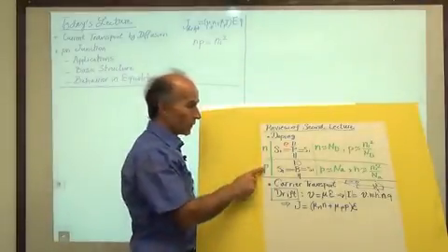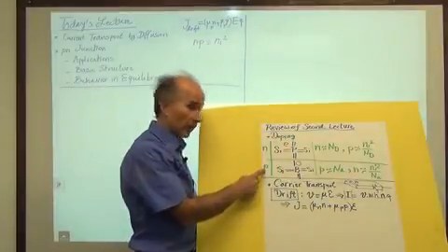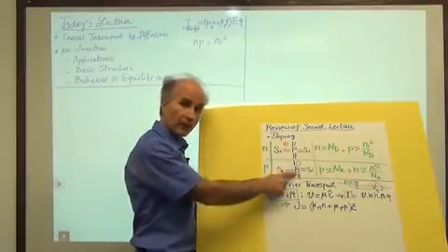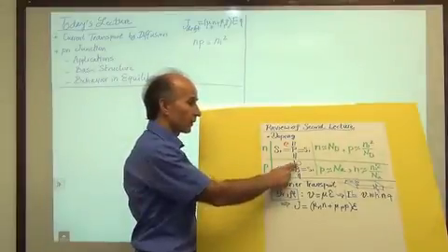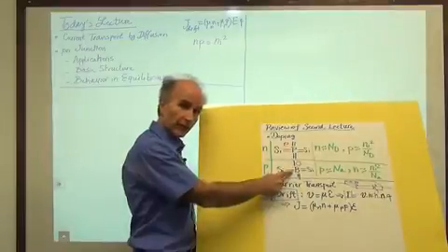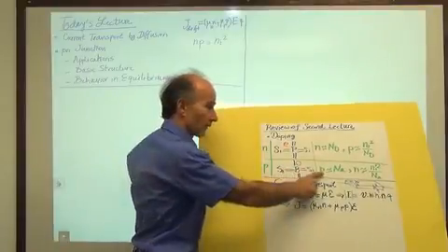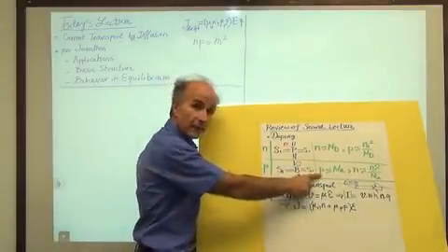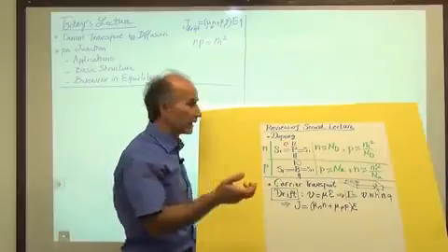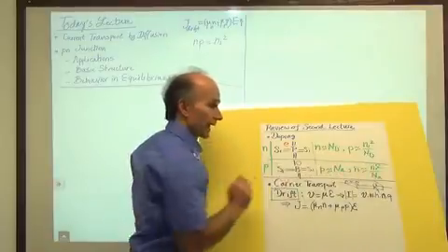Okay, we can also create a large number of holes in a semiconductor by introducing acceptor atoms, such as boron. Boron has only 3 electrons in its outermost shell, so it creates a hole. And we have as many holes as boron atoms. So again, if the density of boron is high enough, we have a hole density approximately equal to the number of acceptor atoms introduced into silicon, and then the number of electrons has fallen considerably to Ni squared over Na.